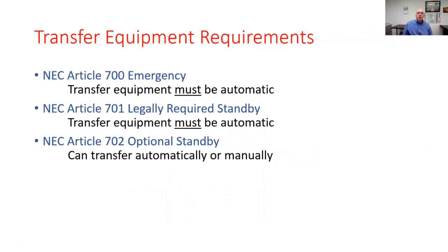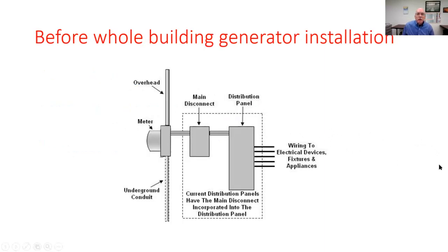So with this, let me go back for a second before I forget anything else. When you put a whole house transfer switch or a main disconnect here, don't forget, let's say this is a 120/240 installation, coming from the main to this sub panel, you need 4 conductors. You need 2 hots, 1 neutral, the grounded conductor, and the grounding conductor. So you're going to install SER cable, or like I said, 4 conductors between these 2 panels.